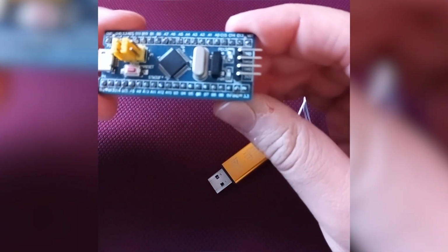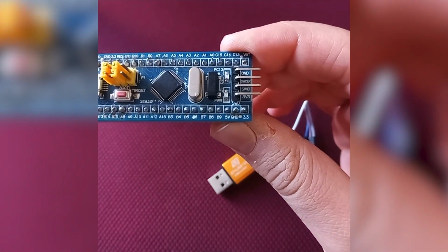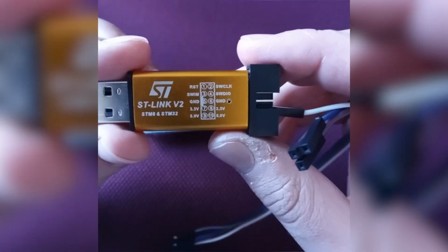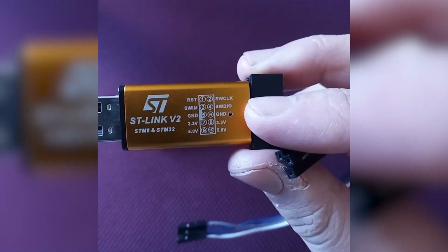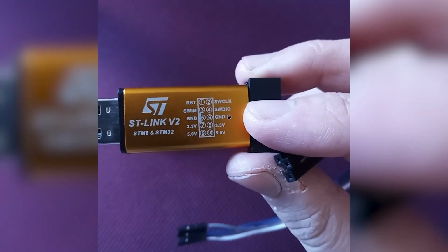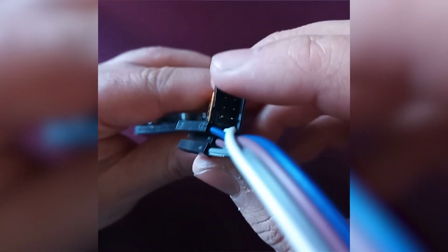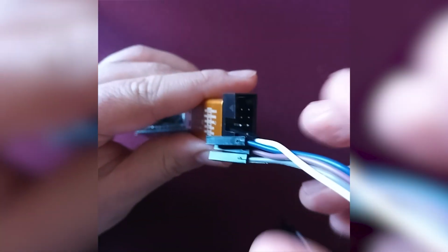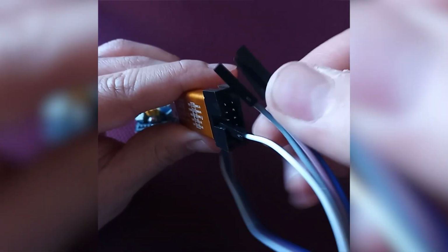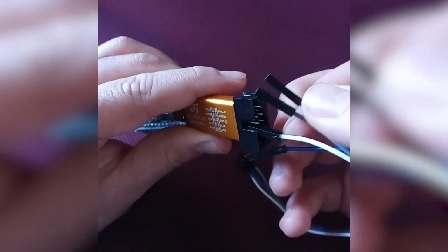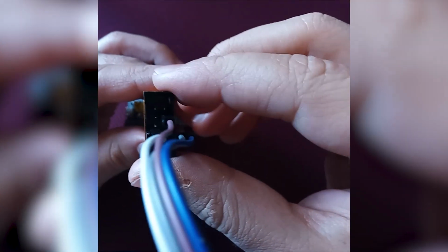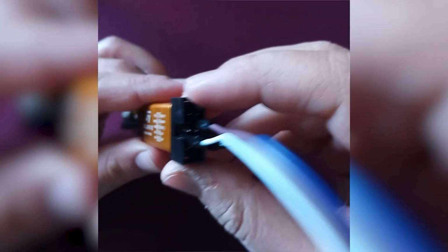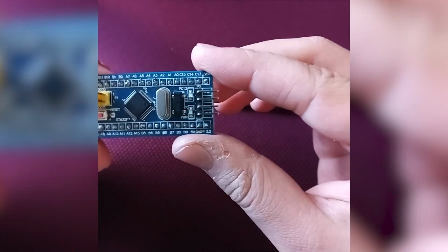What was the next pin? It was SWIO or SWDIO. They are the same, and because not enough space is provided, it has been written as SWIO, but it is the same as SWDIO. It is pin number 4. If I look at this pin, it is 1, 2, 3, 4. This pin. The color that I prefer for SWDIO, of course, is absolutely up to you. It is just personal preference. I pick the purple wire for SWDIO and I connect it to pin number 4. Second column and second row, SWDIO.